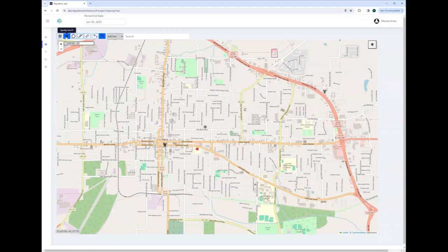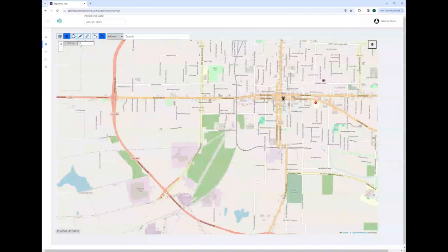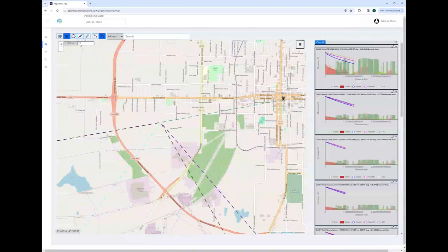So what this does when you qualify a site to point, it wants you to put in a CPE elevation. The FCC, of course, wants us to keep things at 23 feet or below. And so we're just going to go ahead and put that in. Now, anytime we click on the map when we're in this mode, it's going to qualify us to whatever point we click. So I just clicked here. It does take just a second to go out and look at all the points.